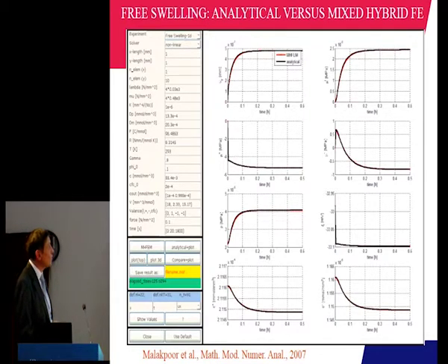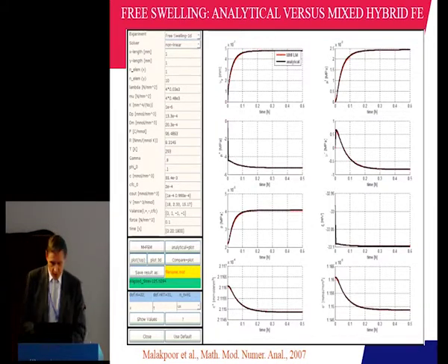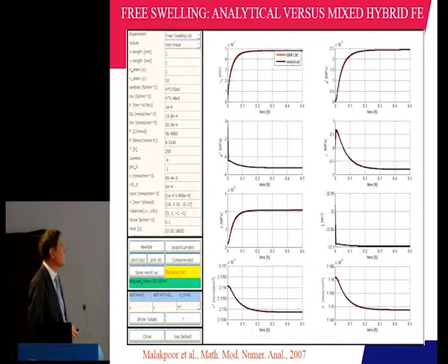For each of the components, we have these ones, and this is a Lagrangian approach using Lagrangian fluxes, 3 of them, because you have the one for fluid, for cations and anions, and you have balance of mass of the whole mixture. This whole analysis is done in finite deformation, and so we have a second Piola-Kirchhoff stress, which is a derivative of free energy with respect to Green-Lagrange strain, like is standard in finite deformation.